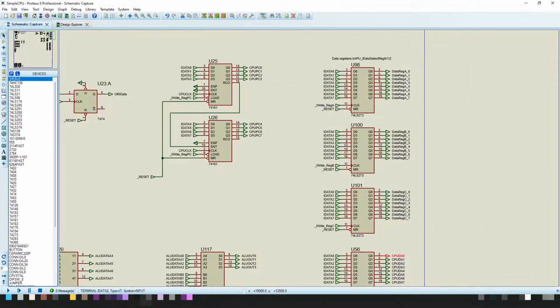And what we can actually show now is that we also have the CPU's program counter. Again, the CPU's program counter is reset with a low on the memory reset value here. And we have set the relevant signals for I want to count upwards, please.